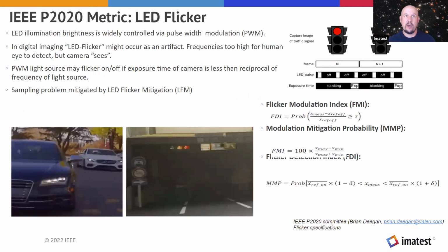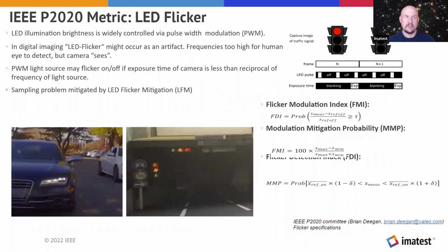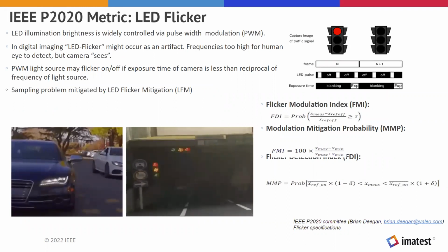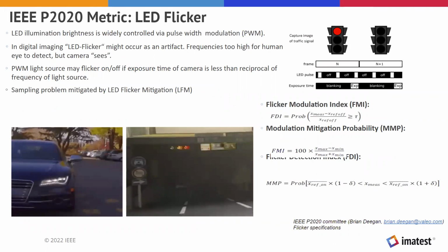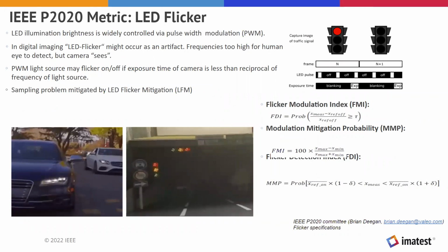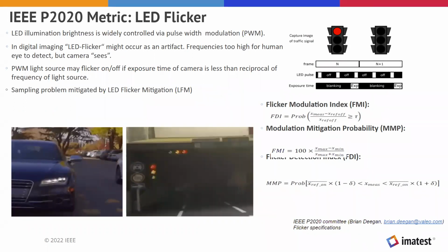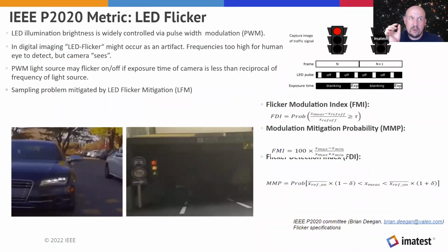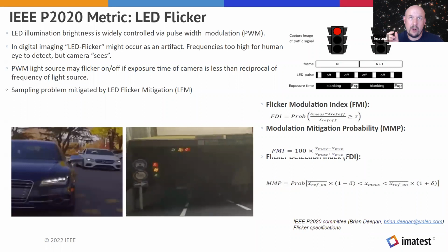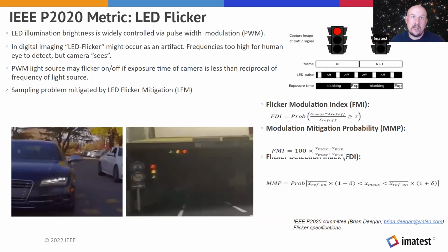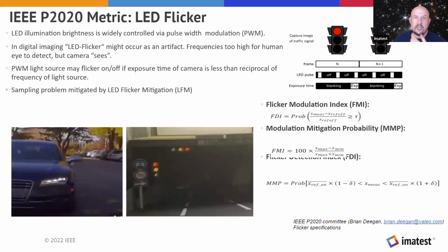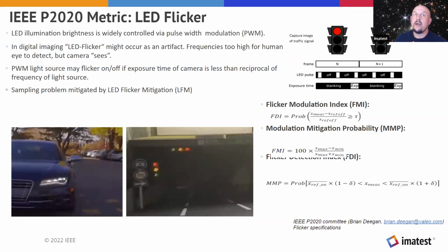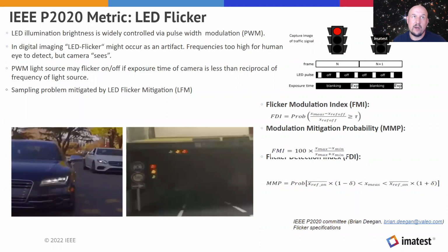And then we're looking at how well an automotive image sensor can mitigate or remove flicker from LED lights. An important one here is LED flicker: can the flicker be captured and calculated? When you're taking a very short exposure from a camera and you have a pulsing LED, those things may not be synchronized, and you may miss the pulse of the LED, and that light may disappear.